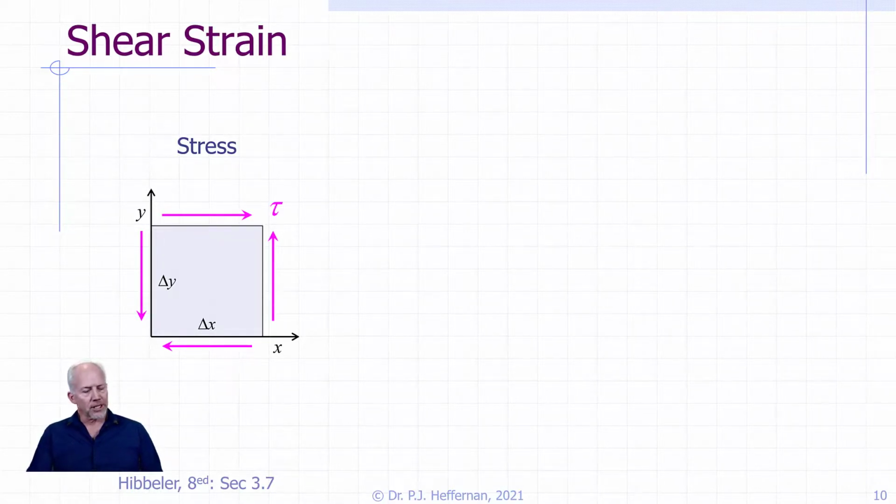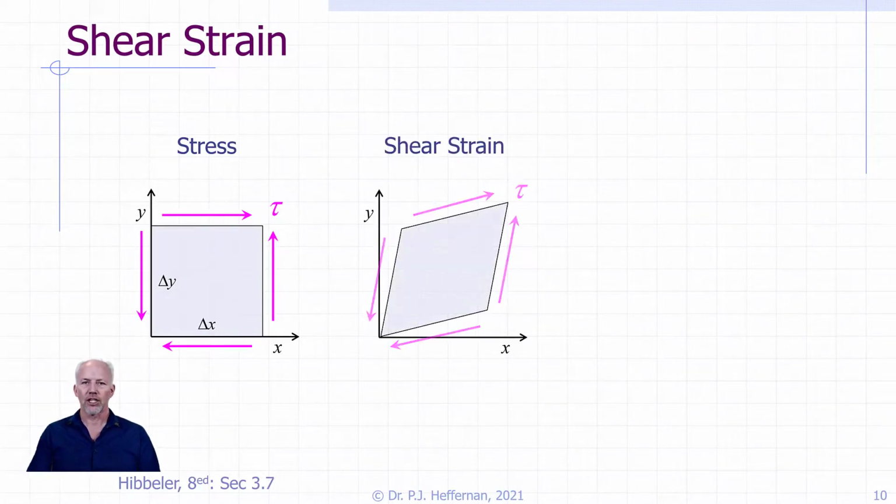If you imagine what that little differential element would look like, if you think of a small sponge and you grip it on the 4 faces where the shear stress is and you squish it, you will see that this is very similar to squishing it by the opposite, or pulling it apart by the opposite corners where the shear stresses are pointing, and you would probably get a deformed shape looking something like this. So our nice little square differential element is starting to look like a little bit of a diamond from this direction.